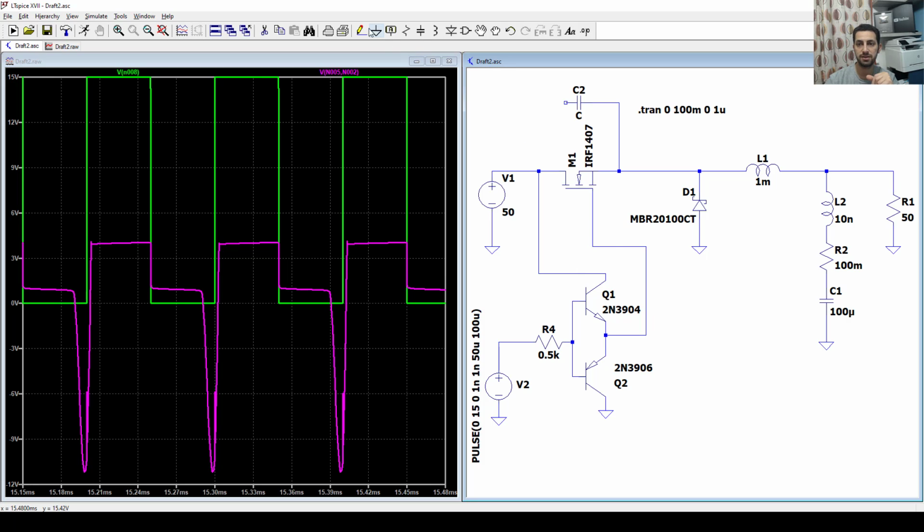Now instead of getting voltage from that node, I will get voltage from that capacitor. If the capacitor is charged, for example, by 20 volt, that 20 volt will be above the source voltage. If I take it and give it to this configuration here, it will drive the gate by 20 volt above the source.